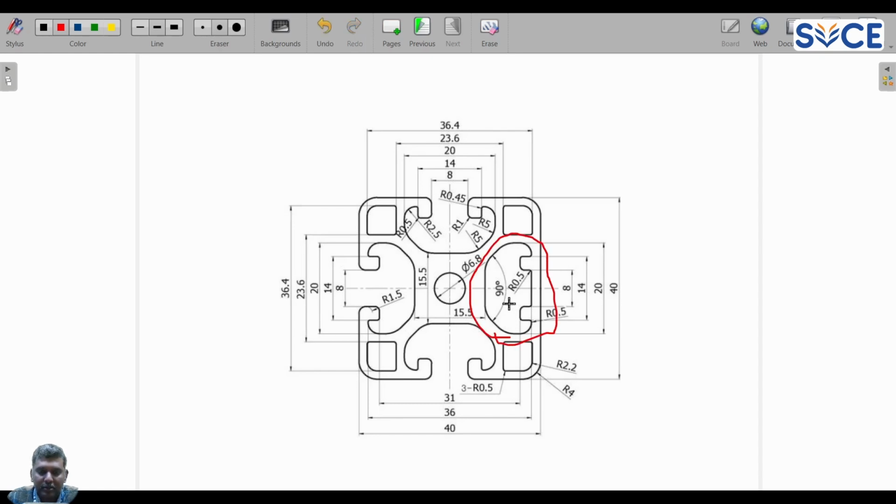this one is repeated on all the sides. So this is repeated here, here and here. So you can think that if you model any one, then we can make a polar array and distribute it in all the other directions. After that, there is only a change in this particular thing, which we are going to remove, and we will change it accordingly, right?